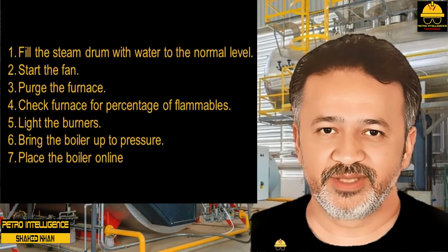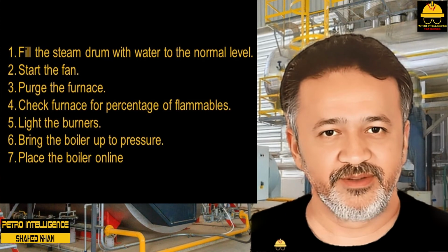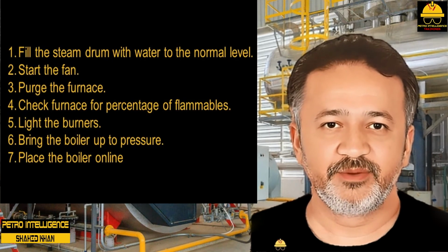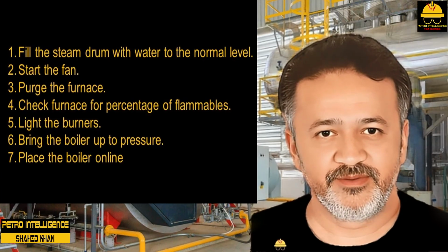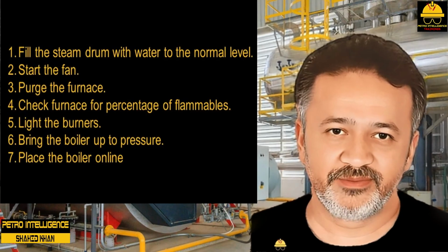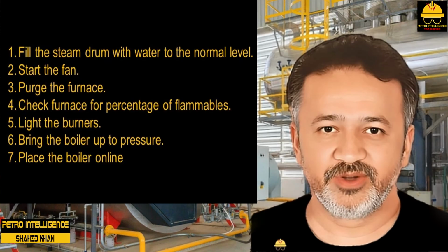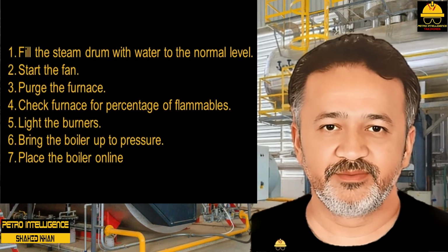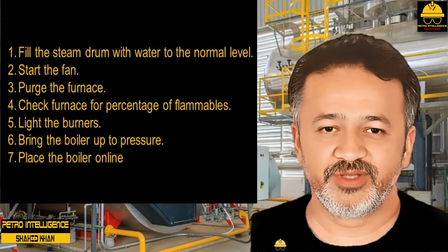Typical boiler problems include tube rupture, soot buildup in superheater and economizer tubes, loss of water flow, flame impingement, frequent or sustained contact between flame and tubes, scale, impurities in steam or water, flame failure, and improper water level. It is usually the operator's responsibility to control water and steam flow rates and temperatures and water level in the boiler. The operator also checks for smoke and checks burner and flame pattern.